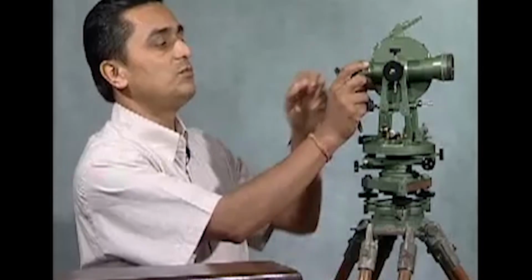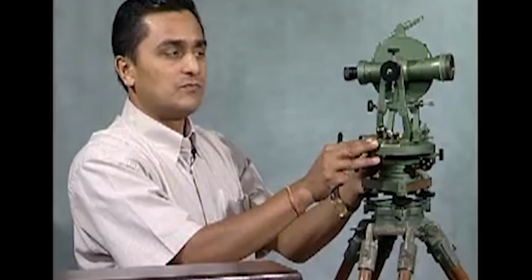So I am bisecting the ranging rod at A. In order to bisect, as we have seen, first we make use of the target sight, because the field of view of the telescope is very small. Using the target sight, I bisect it. Well, that is bisected. I clamp the lower clamp; the upper one is already clamped. Now it cannot move. Now I look through the telescope.